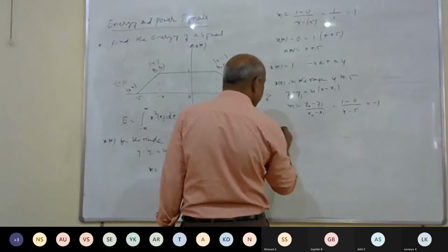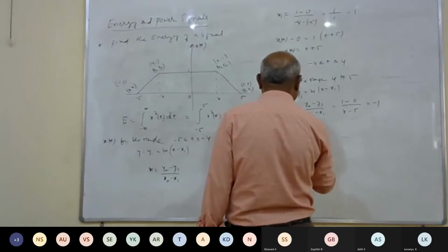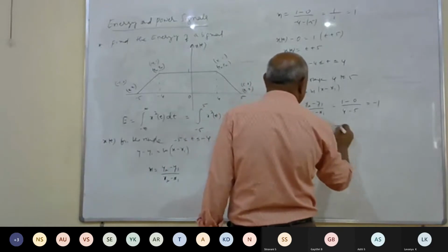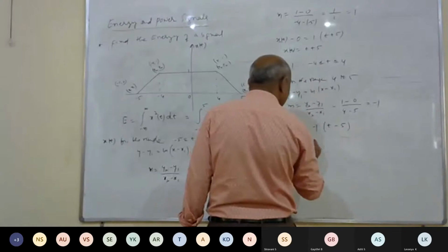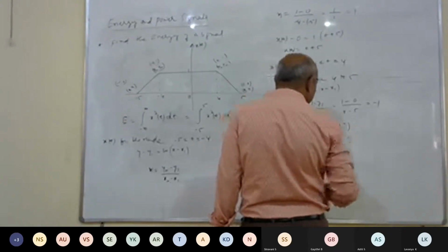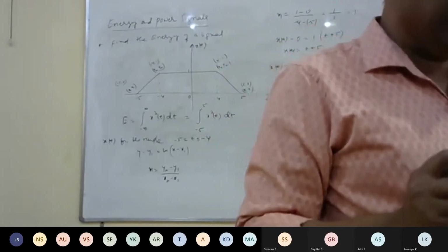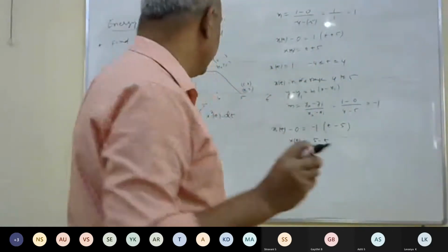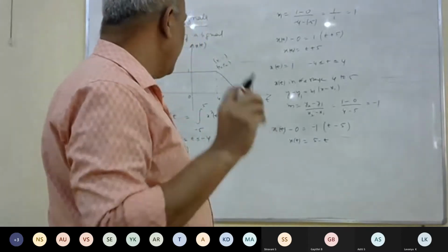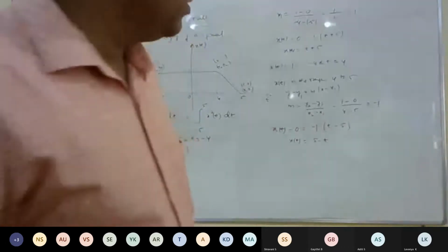Then y is x of t, minus y1 is 0, slope is -1, x is t, x1 is 5. Now x of t is equal to minus t plus 5, that is 5 minus t. That means you have got x of t for the complete range of the signal, -5 to +5. -5 to -4, x of t is t plus 5. -4 to +4, x of t is 1, it's constant. Then 4 to 5, x of t is 5 minus t.